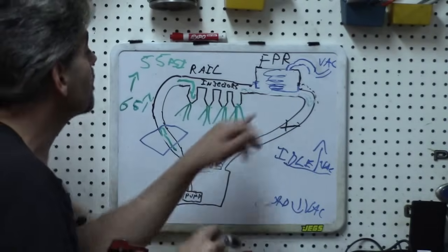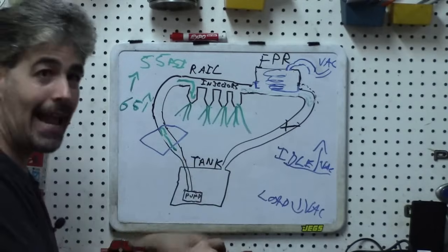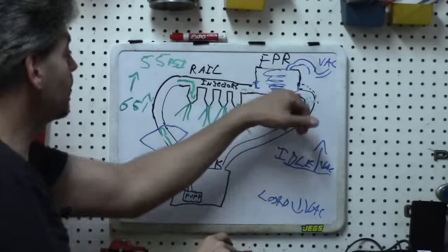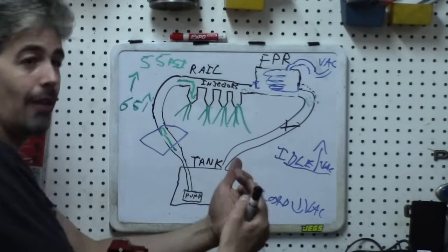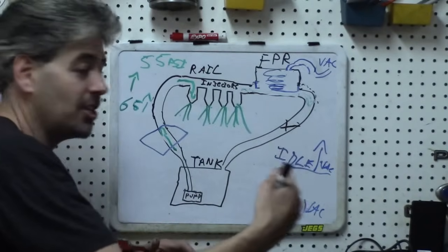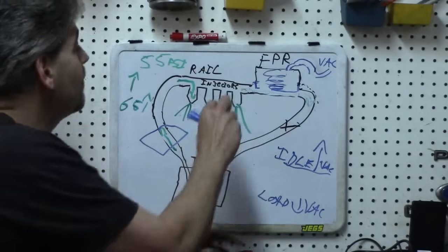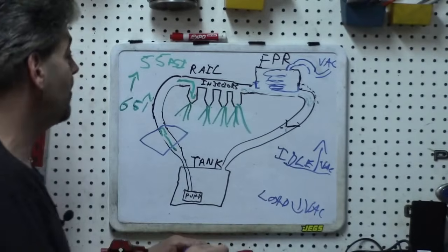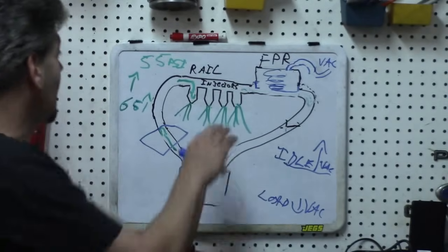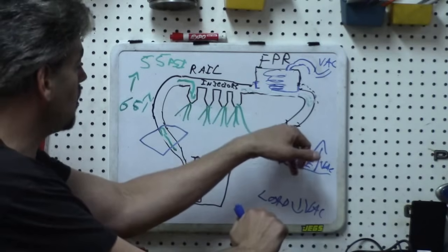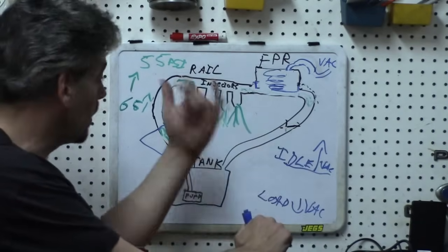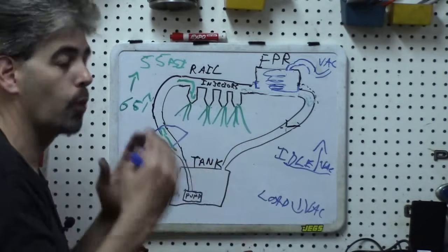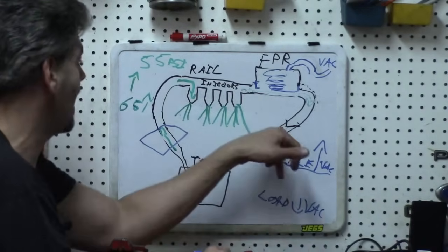So this also will cause a rich condition and low fuel pressure because the leakage is internal, and the internal leakage is of course going to cause a lot of vapor, causing that rich condition, decreasing of course the fuel trim into the negative. So this is a really good way that you would be able to test that, and you wouldn't even need the engine running. Just go ahead and plug up your return line with some vice grips or something like that. I use a special pair of hose clamps. Make sure you only do this on a rubber portion of the line, by the way.